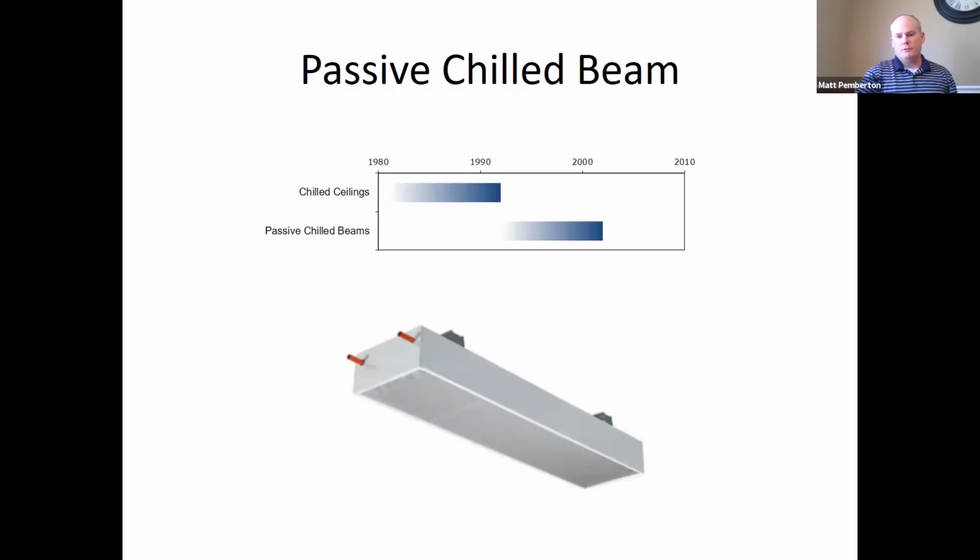So passive beams are typically used in places where you don't need any additional primary air, because there's no duct connection here. There's no induction happening. It's all just natural convection and cooling. And as you mentioned, maybe 300 BTUs per linear foot on the passive beam. Now, you talked before about an induction unit and replacements for induction units. A lot of people have seen the chill beam and actually talked about it being an induction unit just by a different name. But the old induction units we've seen and their replacements are often loud and use a lot of static.